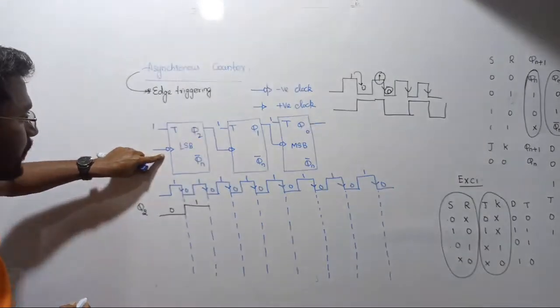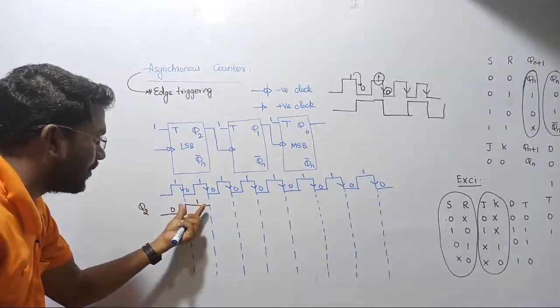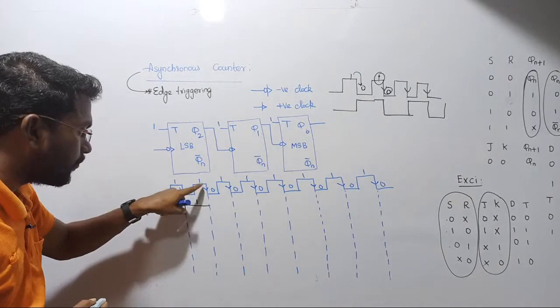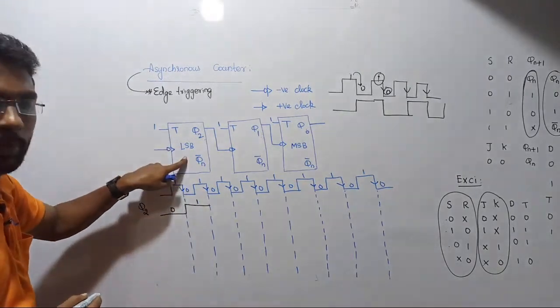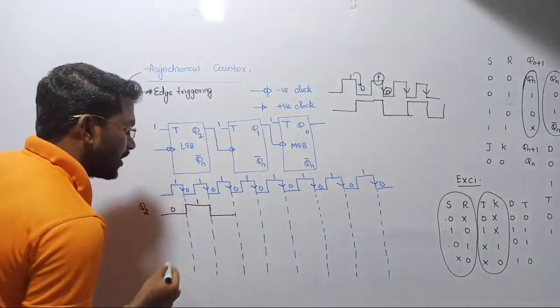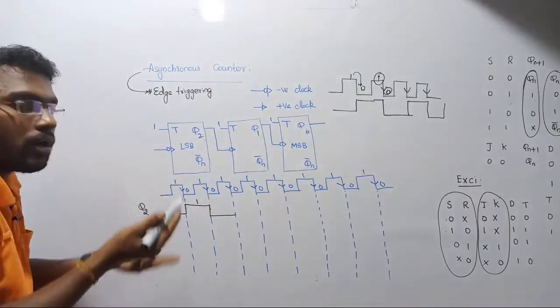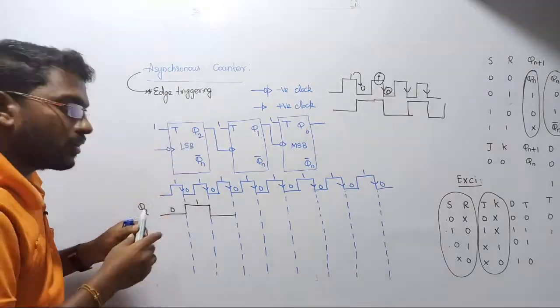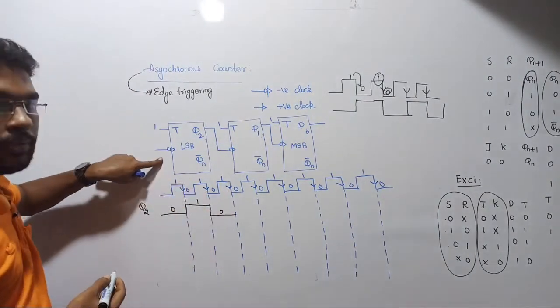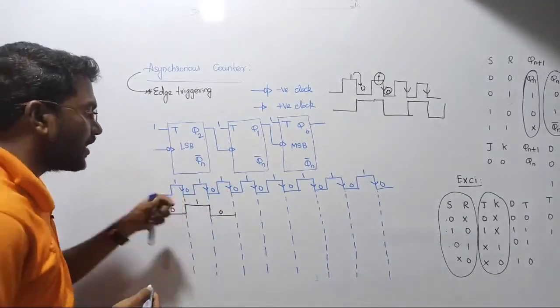See, after a certain time period we give the next clock pulse. That is called the clock time. This is the time where we trigger the same flip-flop once again. Now what will happen? The output of the flip-flop will immediately change from 1 to 0. That is called toggling mode. It keeps on toggling like a spring, right? So next what will happen? Immediately after, again we give a clock here. If you give the next clock pulse, once again it changes.